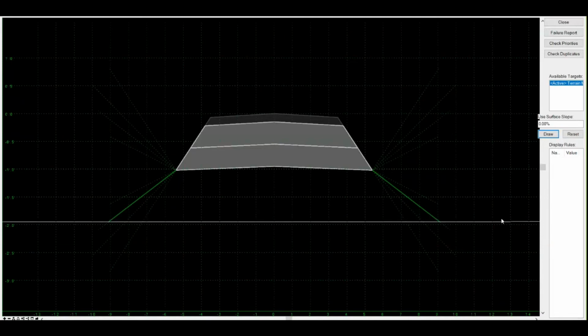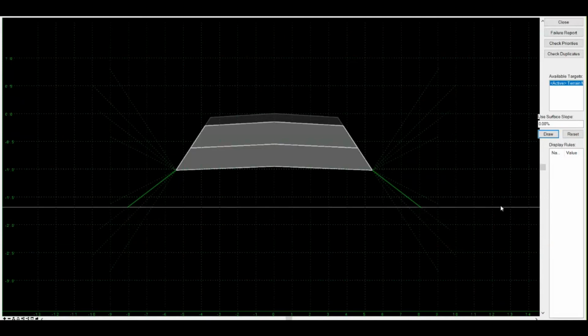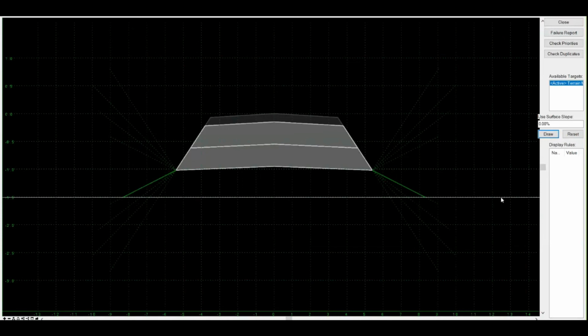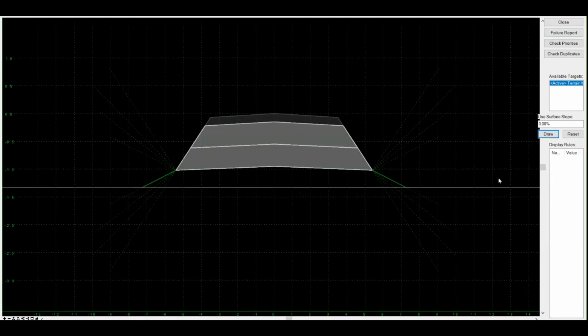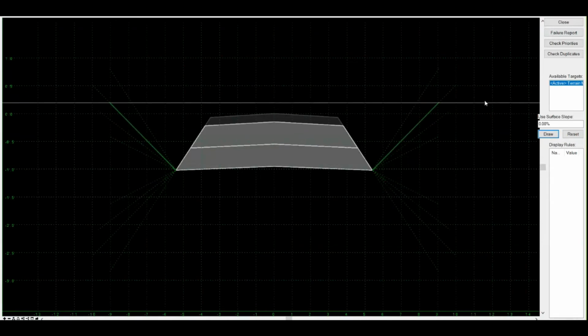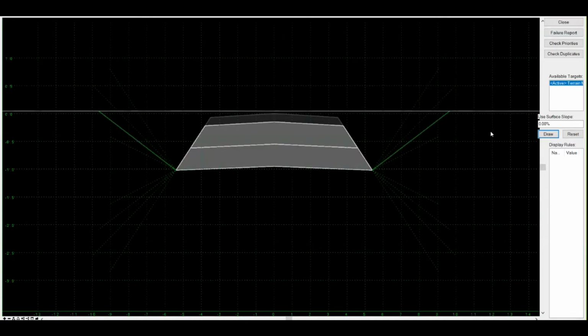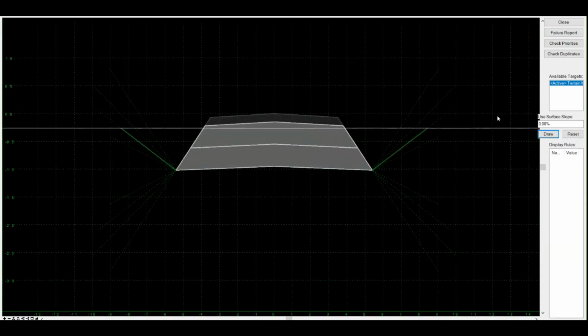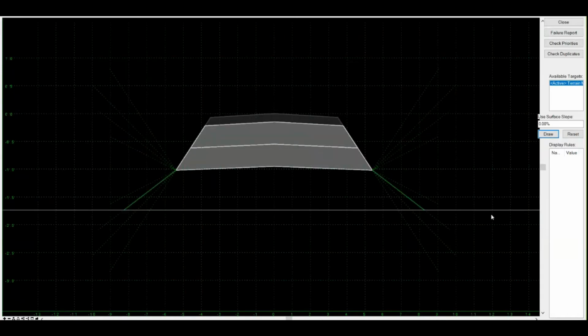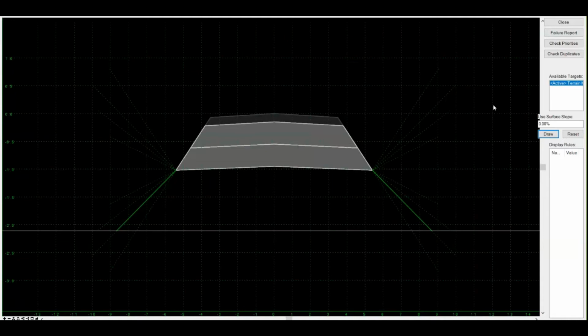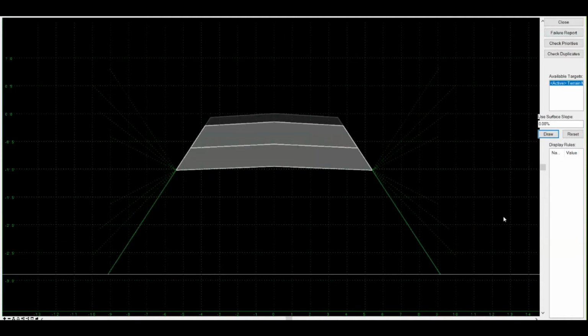Since this is my infilling, if my ground moves a little bit up, the slope lines will change. Now if you can see in the cutting section, as per your ground levels, the slope values are going to automatically snap and take their shape. So this is your testing window in which you can test how your template is going to follow your ground profile.